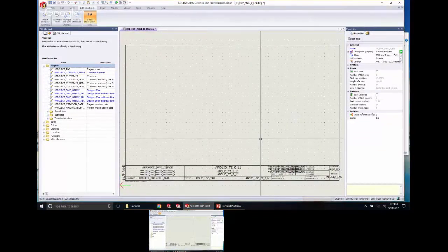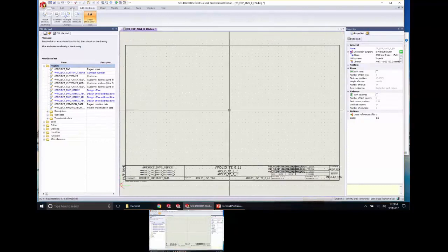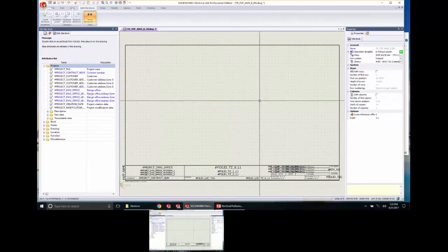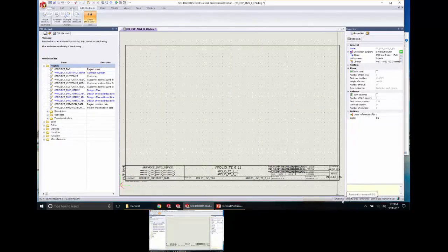Okay. Also down here at the bottom, right? So I'll go into these two panels in a second. Oh, and this is what we call the graphics area, or the area where you're messing around with the drawings. Down here, of course, various layout tools, grid, ortho, snap, grid, turning this grid on and off, ortho, moving in 90 degrees, snap, snapping to a set amount, right?